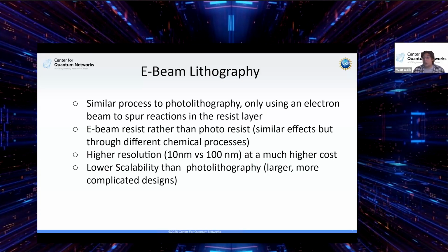So if you're working with something like SOI, where you can make very tight bends, you might want to use e-beam lithography for that. The problem though is lower scalability. And this is one of the big issues when it comes to anything to do with photonics: things like cost, just like anything else you're engineering, but also scalability. How many things can I make? And how fast does it take to make them? So e-beam lithography takes a very long time to do.